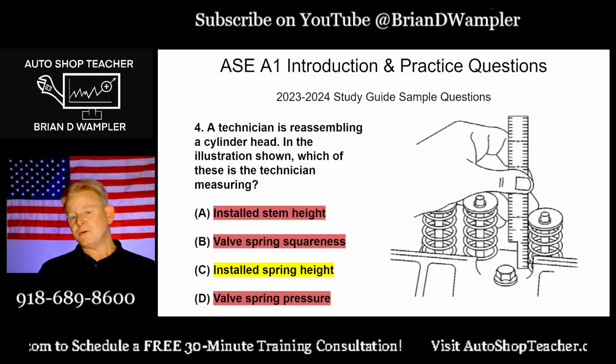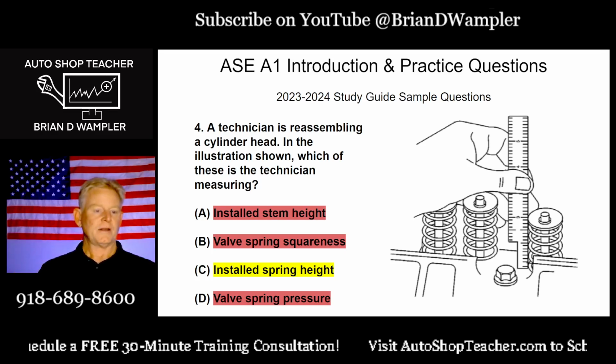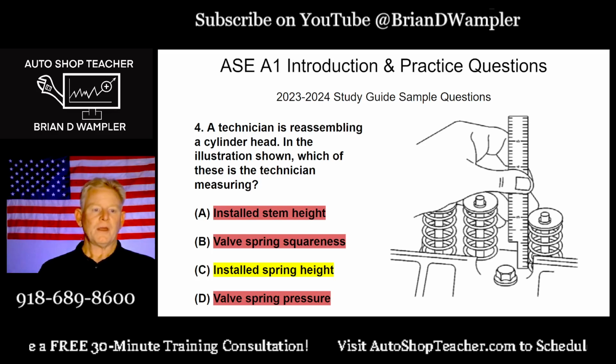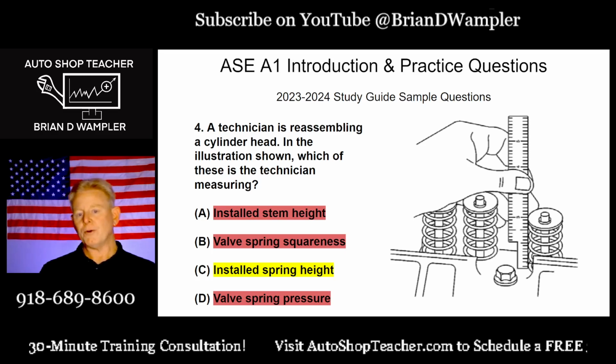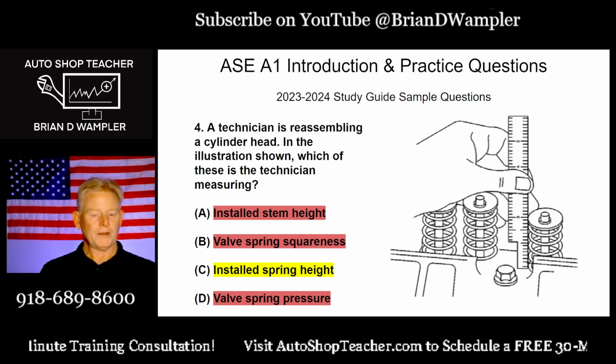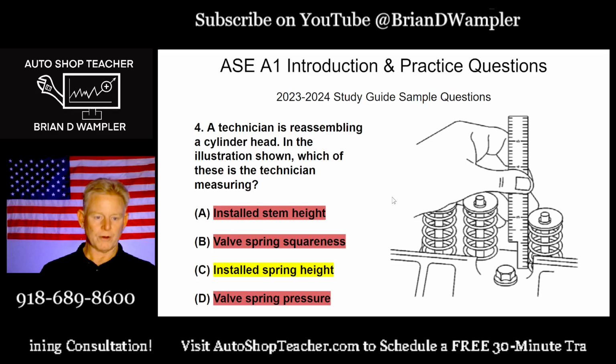But if it's an engine where over the top of this is going to sit a cam carrier with cam followers and who knows what, then the installed spring height is going to be very important and would probably, in my opinion, warrant a more accurate test than just holding a ruler up like is illustrated here.